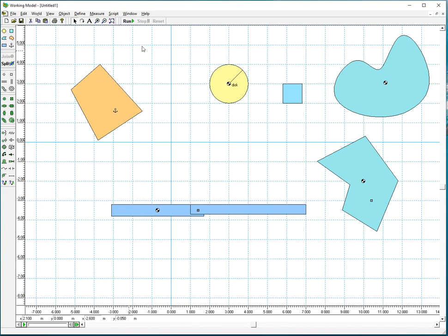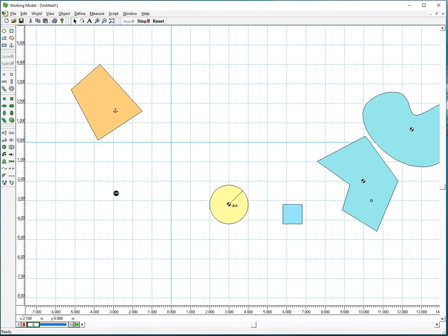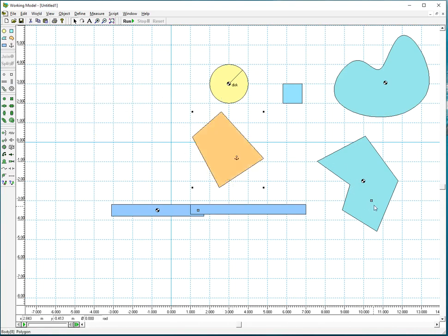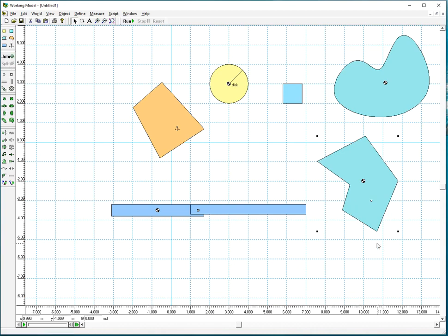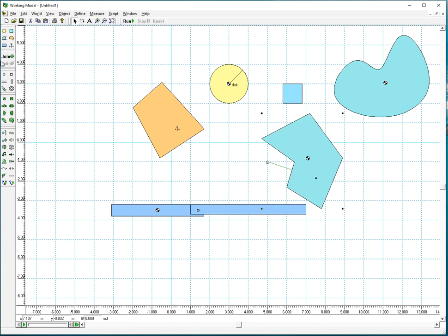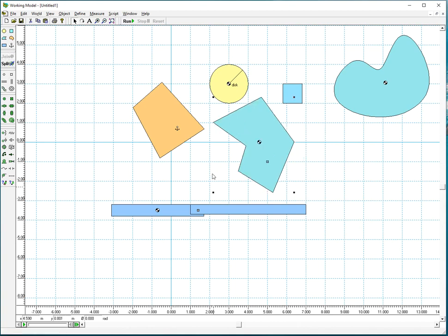I have gravity acting, so if you hit run, they'll fall. You could even see the difference between the anchor and the locked joint is that I need to do something else in order to move this around. That is, use the split function, take the half joint, rigid joint to the ground, and then join it to the new location.